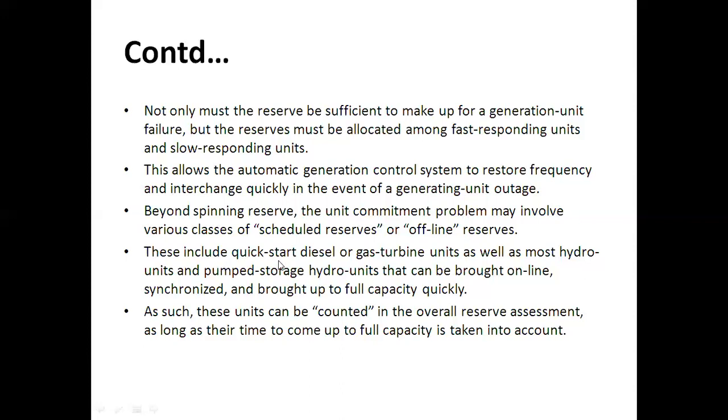These include quick start diesel or gas turbine units, as well as most hydro units and pump storage hydro units that can be brought online, synchronized, and brought up to full capacity quickly. These are the fast responding units that we have to keep in mind in order to do the spinning reserve computation.